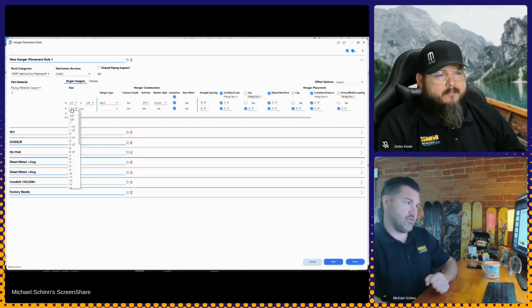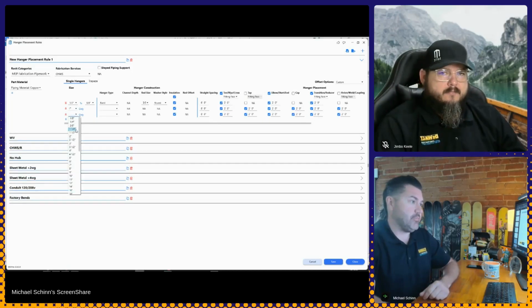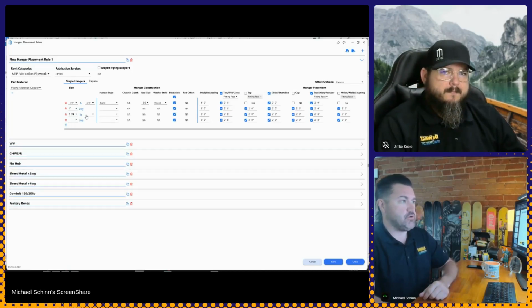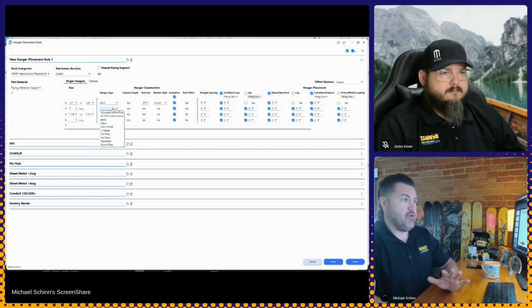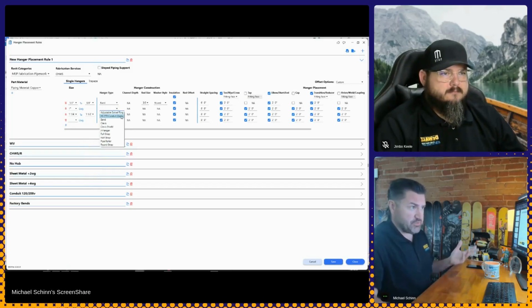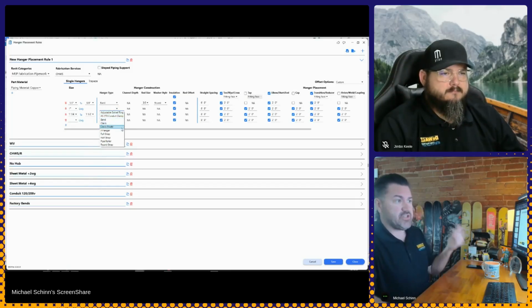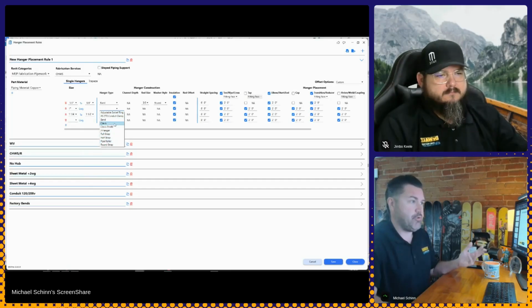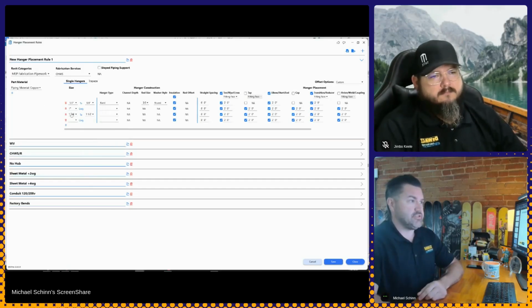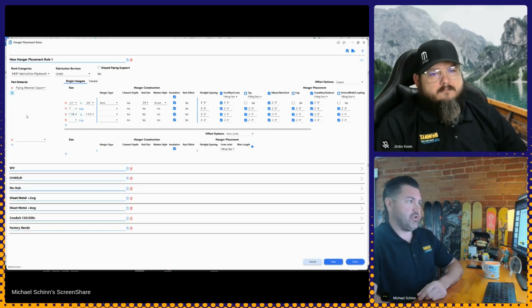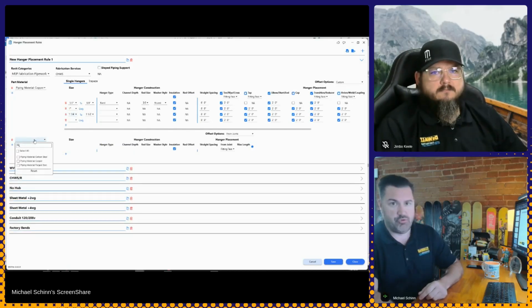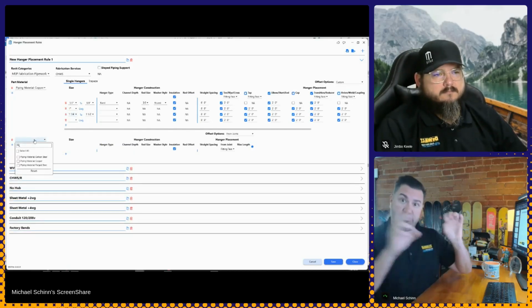Now let's do another size range. Let's do 1 inch, and you can do another one from 1.25 up to 1.5. We can then do your adjustable swivel, you want your band, you want a clevis with a shield, a J hanger, or a pipe roller. Fully customize exactly how you want your hangers to be. So this is for copper. Let's hit another plus button here, and now let's make another sub rule in here for basically a sub material rule.